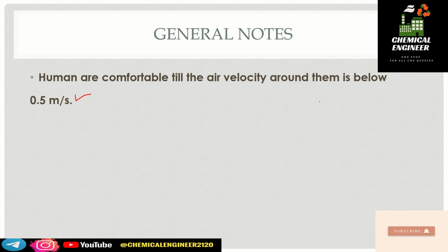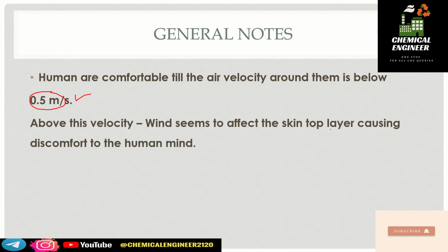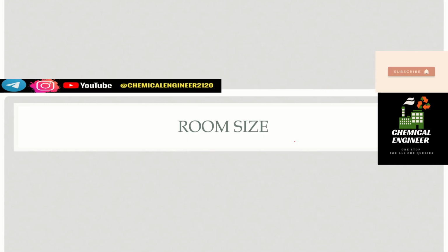Moreover, those higher velocities are not advisable because they are not actually good, as some pollutants may get entrapped in the fan airflow and may directly come towards you. So a velocity lower than 0.5 meter per second is advisable or recommended. Above this velocity, the top layer of skin feels discomfort.